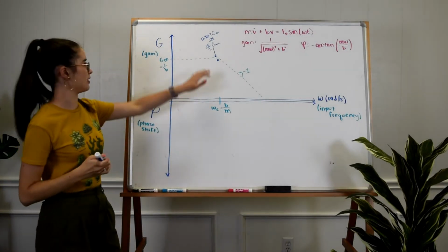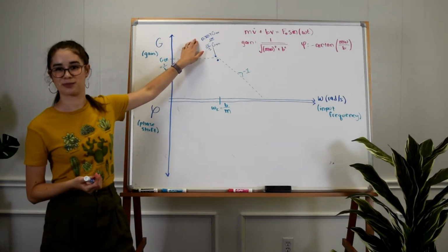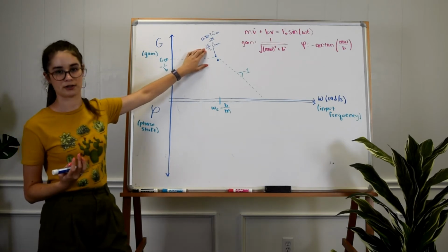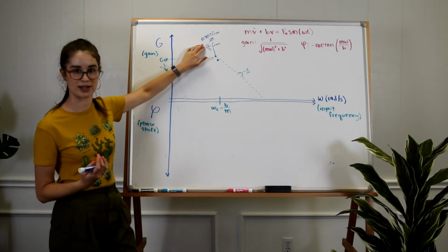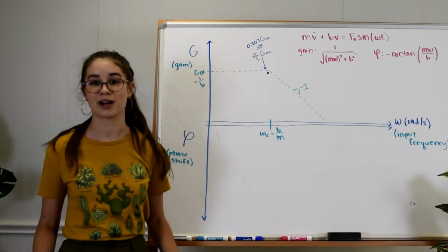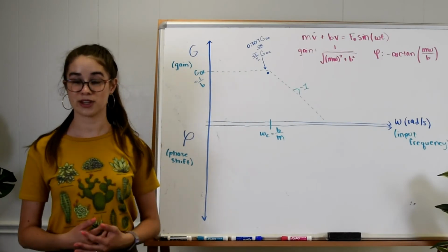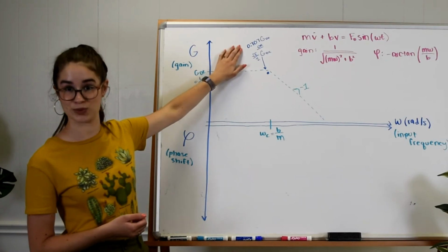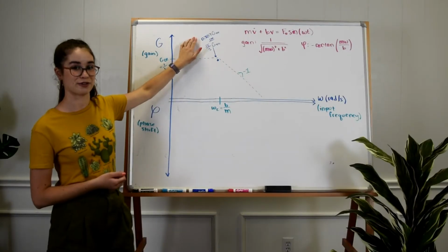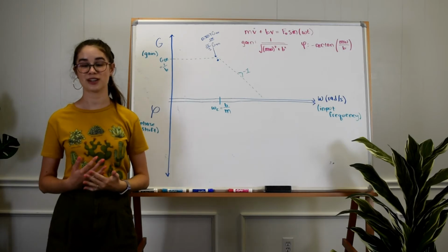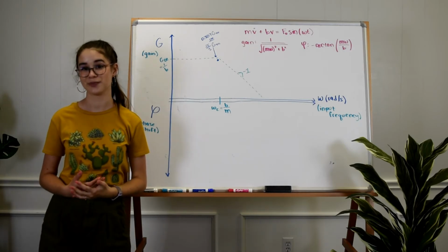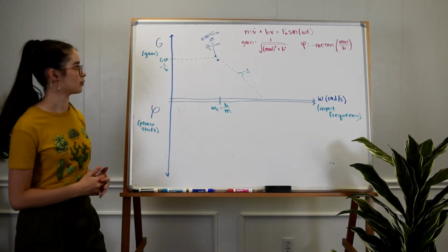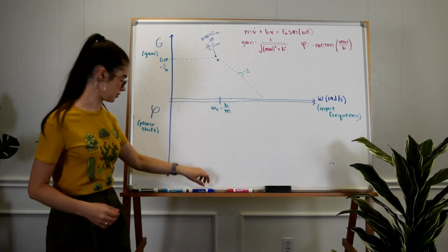We just use 0.707 as an approximation because it's a little bit easier than having to do square root of 2 over 2 every single time. But these two things are the same. Something to note here is that for any order system, the point where the gain changes by 0.707 is called our bandwidth. It just so happens that for first order systems, this point corresponds with our eigenvalue, which is super convenient. Finally, to finish drawing our gain, we just draw a line that follows our asymptotes.